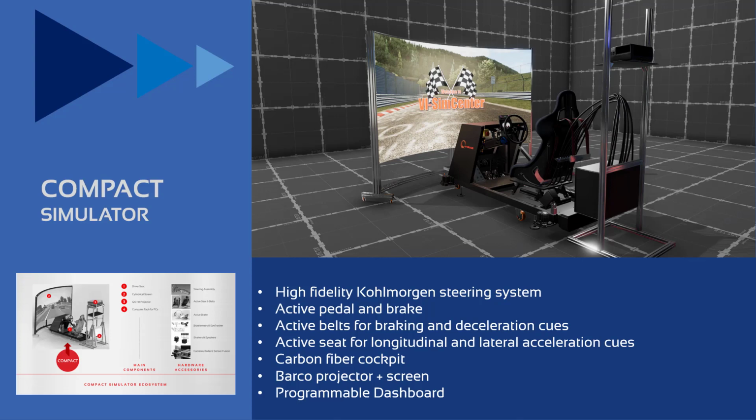Similarly, we support active throttle and brake pedals capable of tuning to get design intent pedal feel. We include optional active belts to provide braking and deceleration cues directly fed from the simulation model. Similarly, the active seat contains multiple air bladders that an experienced driver uses to feel the lateral and yaw response of the model being driven. The solution uses a Barco projector with screen to provide a wide visual view. The Barco projector also functions as a replacement backup for DIM dynamic simulator customers that also use Barco projectors.